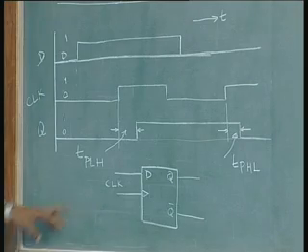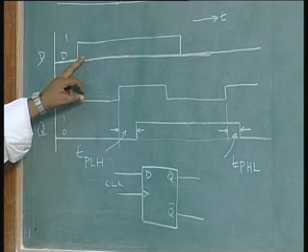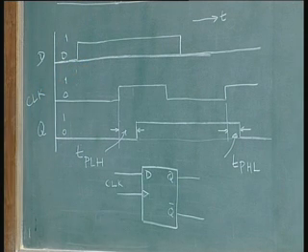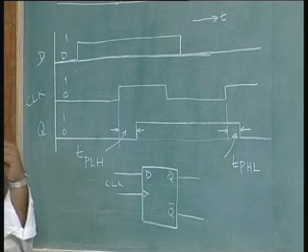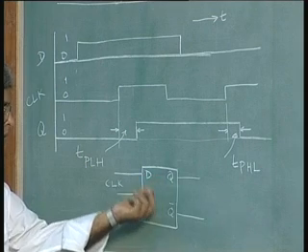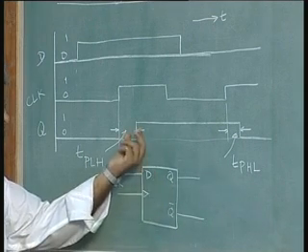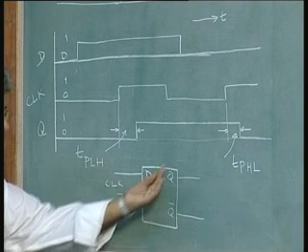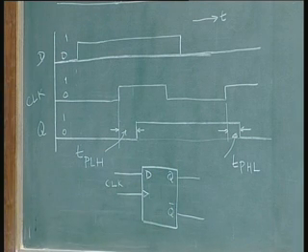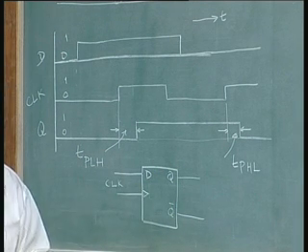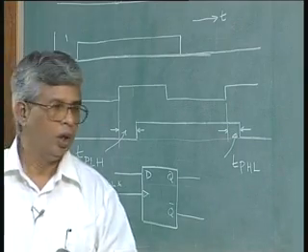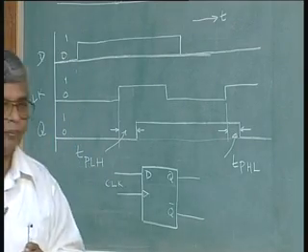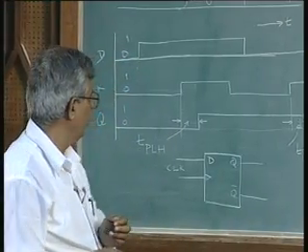Now, the one other thing is, this is purely the output propagation, the propagation of the signal through the gates inside the flip-flop to the output. There are a couple more timings we have to be concerned about. One is called the setup time, the other is called the hold time. We will define this.